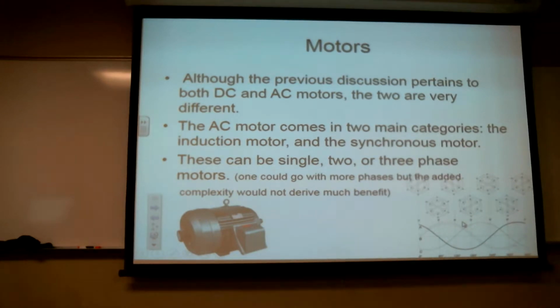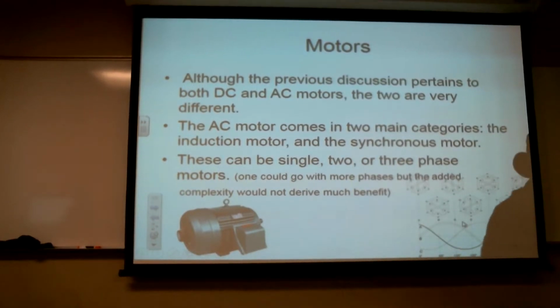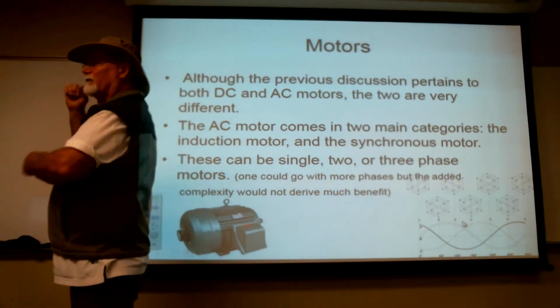All right, AC motors. So in a DC motor, we talked about the notion that we have to feed it some DC, and we're going to have this switching device called the commutator. Every time the current is driven through some set of the armature windings, those windings create magnetic fields which act against the lines of force. On one side they pull, on the other side they push, and that forces this spindle round and round.